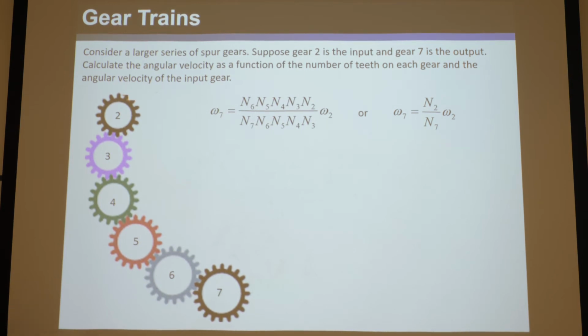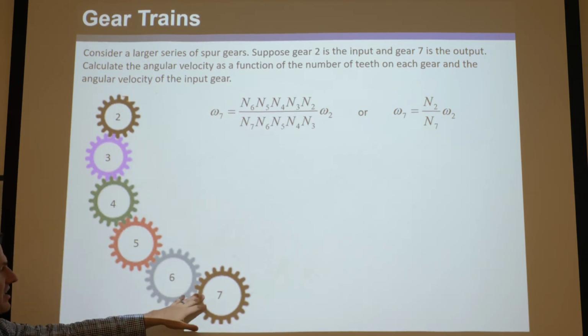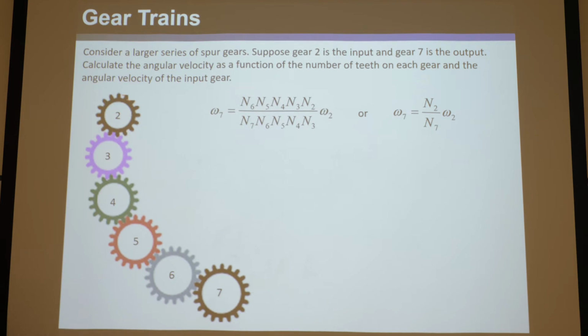You could spread any 2 gears out as far as you want, and they would still mesh as long as their radii are huge. They'd take up a lot of space. So the way you could get rid of that space and still have hugely far apart parallel axes is to make the gears small and put in a bunch of intermediate gears. So that's the only reason you'd ever want to do this. But usually that's pretty stupid. You wouldn't want to do it, okay? You're not getting any mechanical advantage or geometric advantage from it at all. You're just adding a lot of friction, okay?